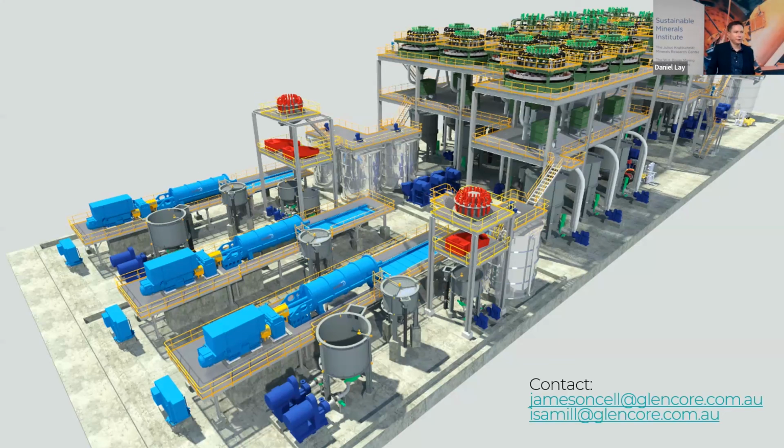Yeah, so for a Jameson cell, it's quite simple. If you simply reduce the feed by half, the recycle will automatically adjust. So it maintains a constant flow through the downcomer, and it will just recycle more tails to compensate for the lack of feed. So there's not actually something that the operator needs to do as such.